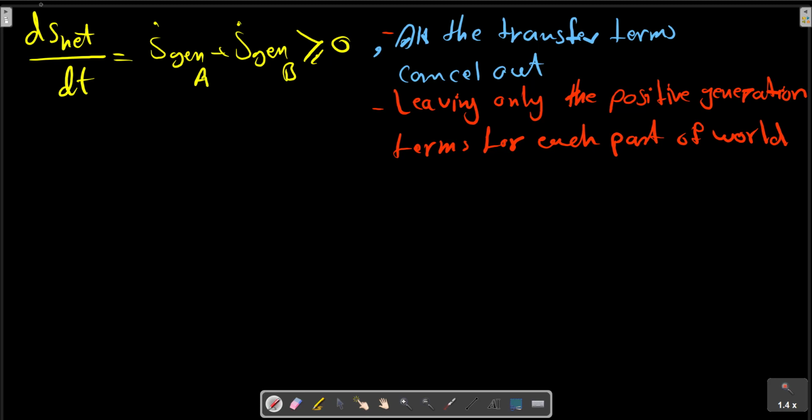However, we also notice that for the heat transfer to move in the identical direction, we must have T be greater than Ta. That is, the heat transfer takes place over a finite temperature difference. So an irreversible process occurs in the surroundings. Such a case is called an external irreversible process.